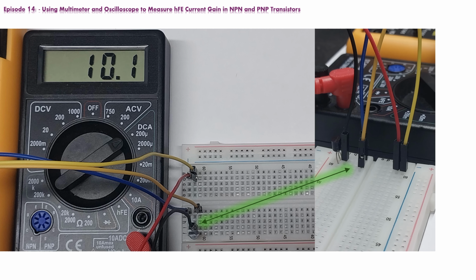We will position multimeter probes between the base slot of the hFE port and the base terminal of the transistor. We will select DC current measurement, in microamperes range on our second multimeter. We measure between 10.1 and 10.2 microamperes of base current. DuPont wires from the second multimeter are the red and black ones. So, this is our base current measurement. Now we have VCE voltage and base current parameters.